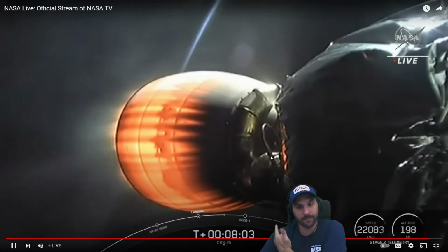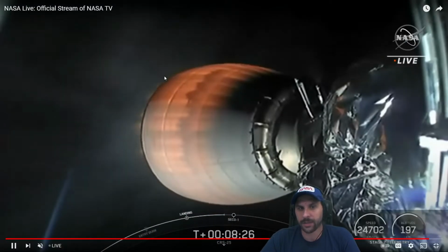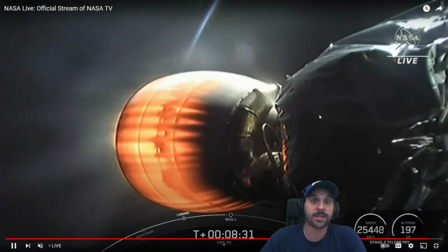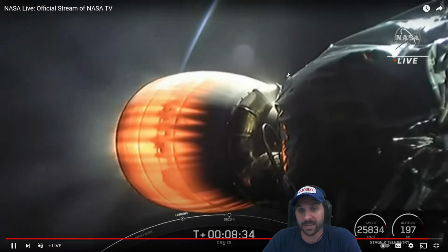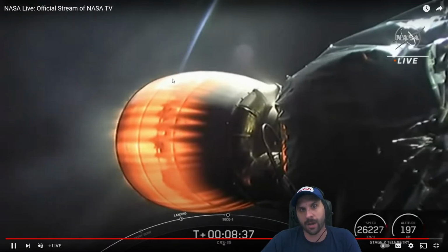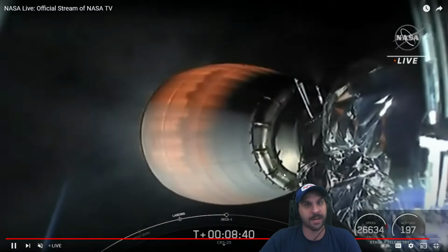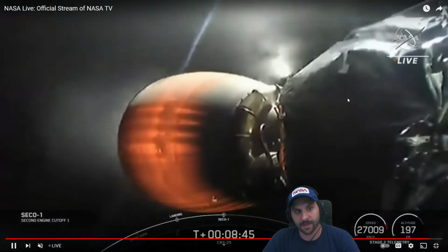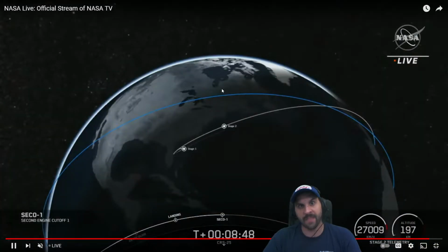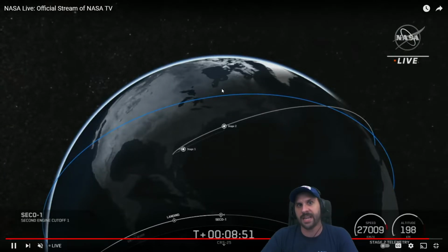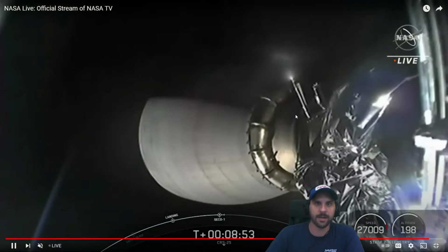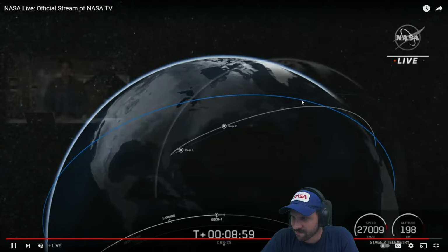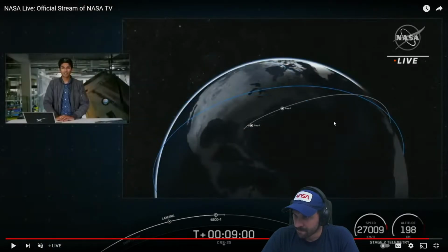If you watch here even more, if we get the second stage engine cutoff, they'll shut the engine off and you'll see the purge lines. You'll see the purge lines on the second stage do the exact same thing. They pump helium into the engine to get all the liquid oxygen out, because even a 5-10 minute coast for the second stage with liquid oxygen in there is enough to rust it, to break things. So watch, they'll shut the engine off and you'll see a puff of gas come out. See? And then the purge lines will turn on and they'll hit helium into the engine, there it is, to get all the liquid oxygen out of there. Pretty cool, huh? Little lesson on propulsion there.